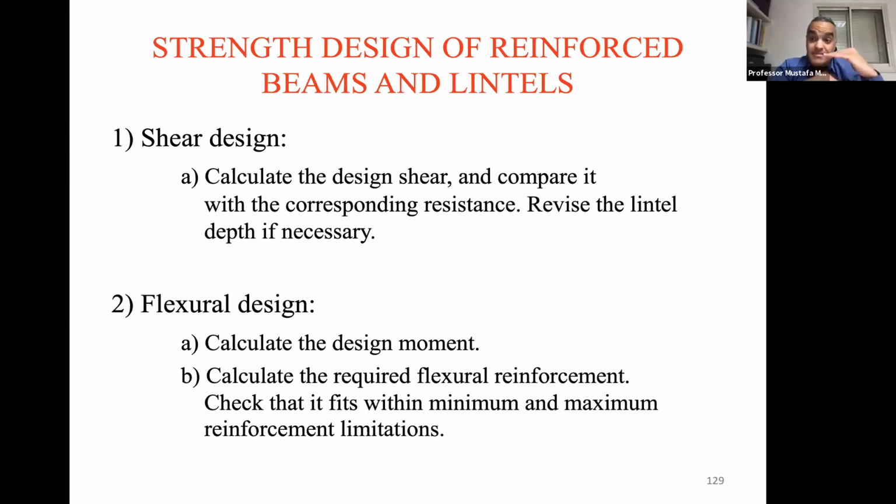That will determine the depth of the lintel that we need to use in our design. If it's not, then we can use shear reinforcement. For the flexural design, calculate the design moment, calculate the required flexural reinforcement, and check, again, this is using the rectangular compression block in the masonry that we showed in the free body diagram before. Check if it's within the maximum and the minimum reinforcement limitation.